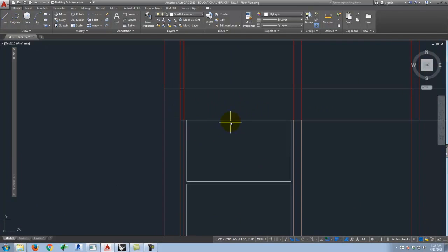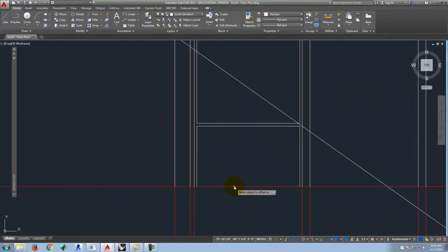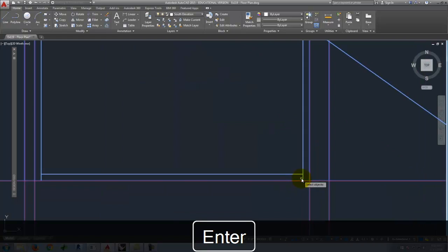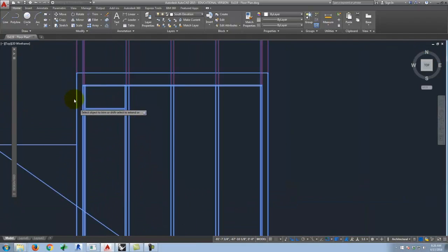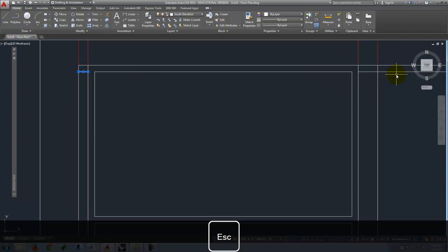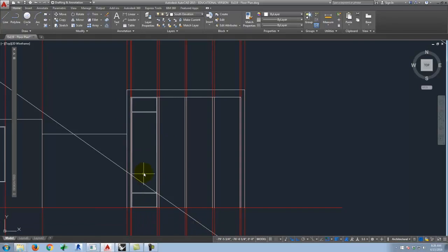So I can go back and do an offset again. 1 inch there. And I don't really have a line to do at the bottom, so I'll have to just draw up a line 1 inch over. And we'll do a trim again. And I just typed all after I typed trim so that it didn't actually have to select anything. Come up here. There. Delete. Delete. Okay. So I've drawn in what those windows look like, and maybe I need one more division in